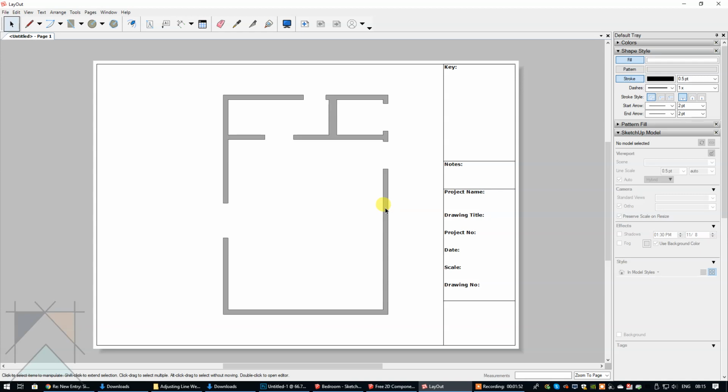And what I'm going to do, guys, is I'm going to create 3 pages. A page for the walls scene, a page for everything else scene, and a page for all. And that's when I'm going to combine those 2 different elements of the floor plan into one floor plan on one page with the different line weights. Okay? And to correspond with those 3 pages, I'm also going to create new layers in layout so that I can actually assign the different line weights.